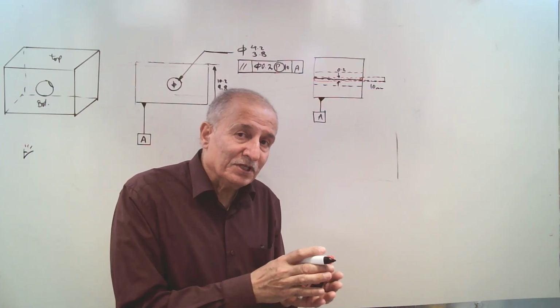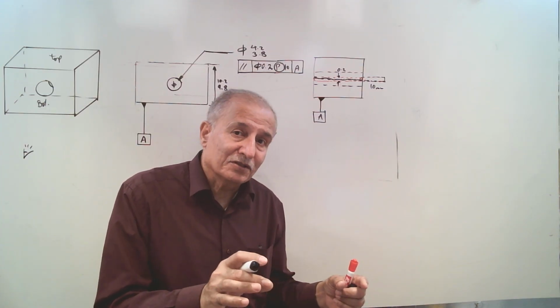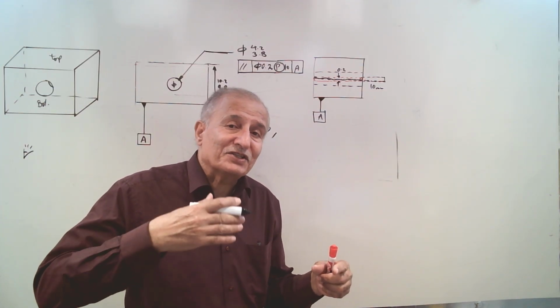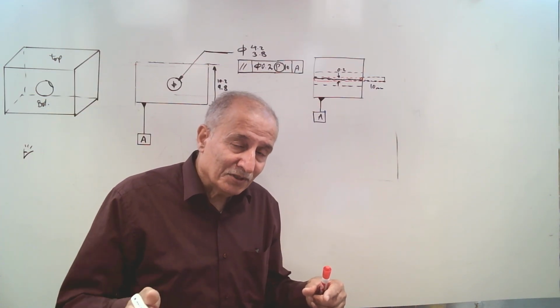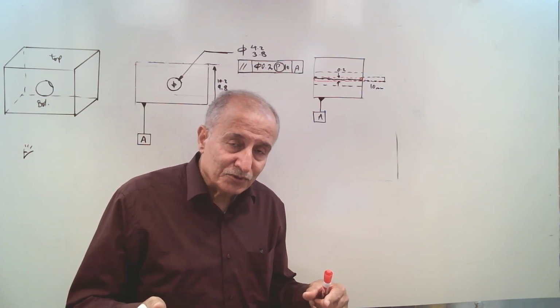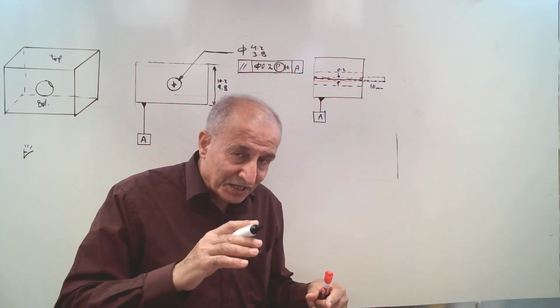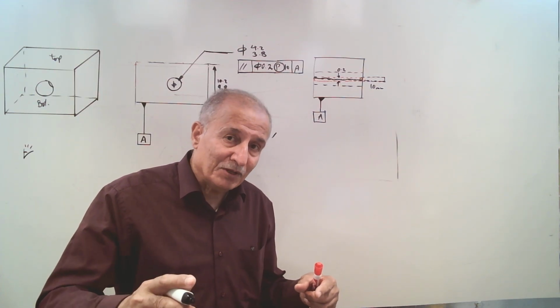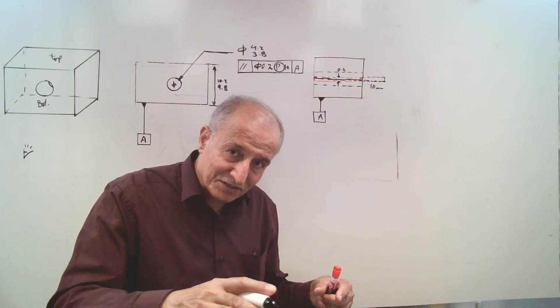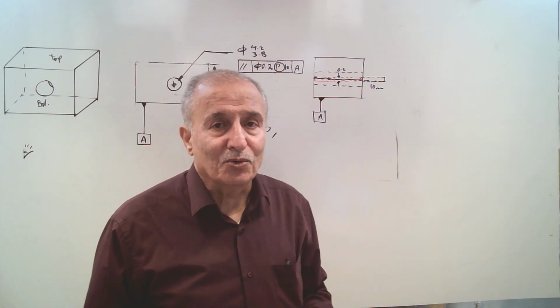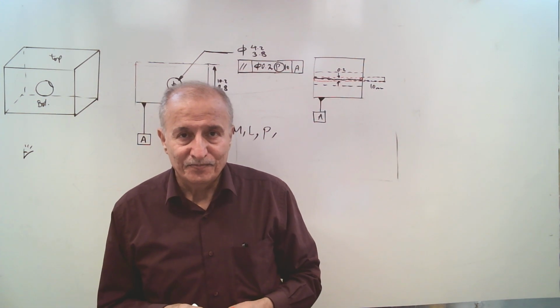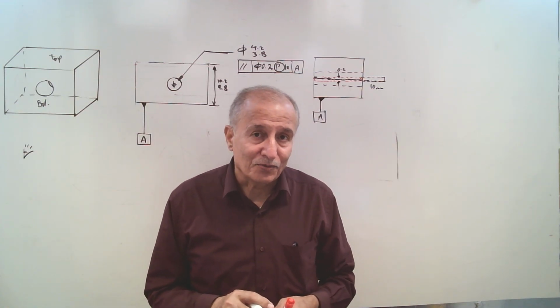Not only must the axis be in the zone inside the object, but also if I extend the axis, for example, 10 millimeter outside, and extend the zone as well 10 millimeter, the extended axis must lie in this zone. This is called projected tolerance zone.